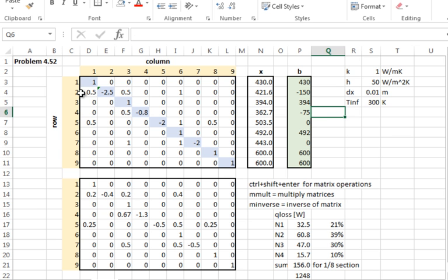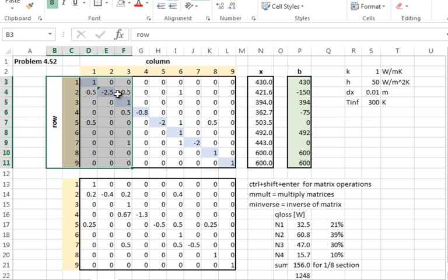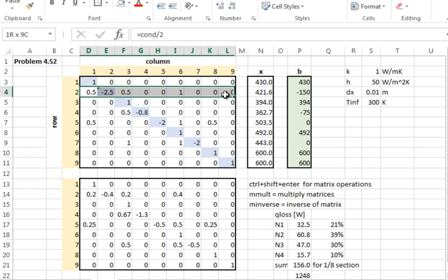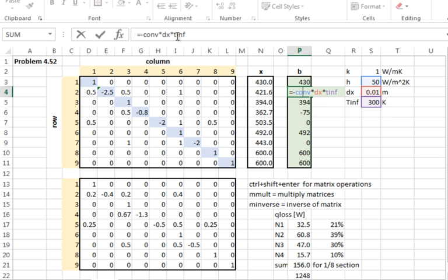And then this is an energy balance for the second node. Right there. And notice that the second node plays with 1, 3, 6. But also way over here on the right-hand side, that's where T infinity comes in. Can you see that? T infinity comes in right there. So I wanted to go further than I did. Sorry about that. But I encourage you to set it up as a matrix problem and solve the homework problems that way that are